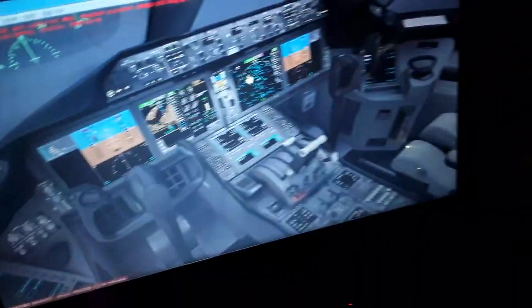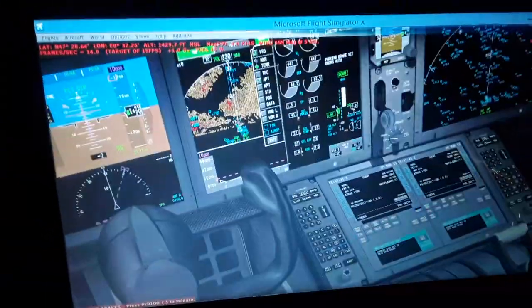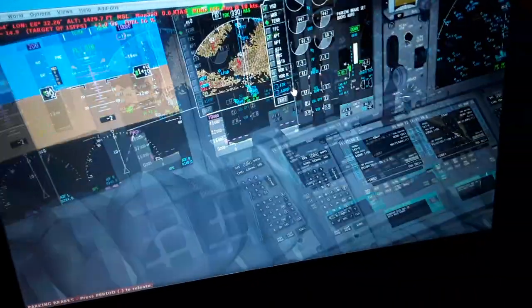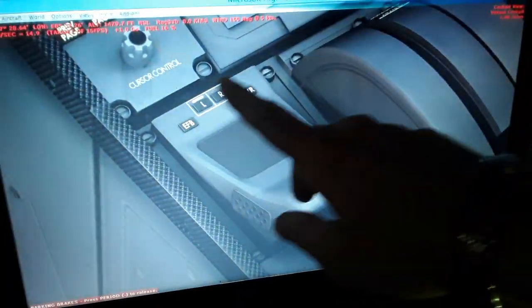We're gonna tune this either manually using the flight management computer. You can see the flight management computer over here, so we'll use that to make a flight plan. It will be displayed here in the navigation display, also in the HSI. I'm also gonna use it to tune the radio frequencies for the LSZH localizer.